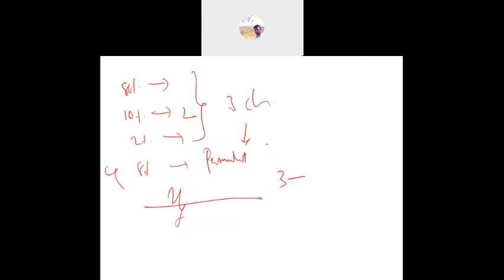And one more thing: in the circuit breaker division, automatic reclosers are not used in cables, as they break down the insulation of the cable. If a failure occurs in a cable, it is mainly because of insulation failure. If the insulation fails, it becomes a permanent fault.